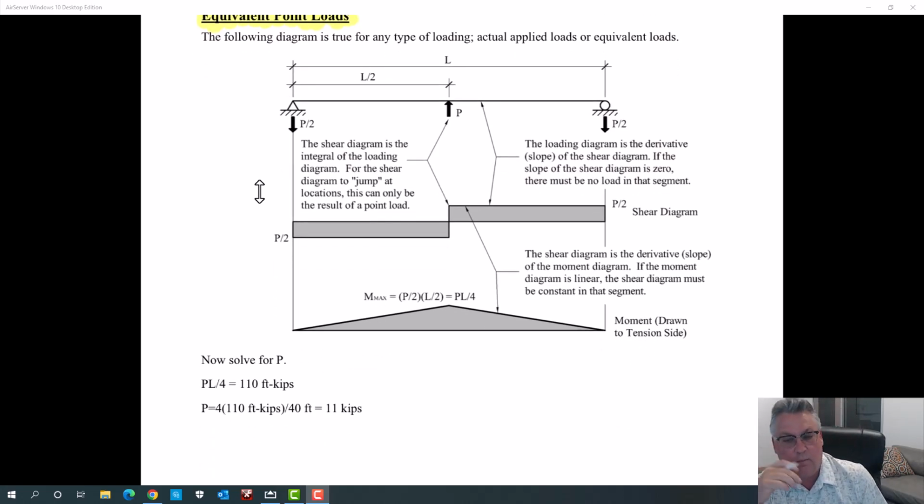Right now you're asking, well, why would you want to do that? It's so easy to just create it, multiplying the force times the eccentricity, but that's what we're here for, and that's what your first couple of homework assignments will show you. But when T.Y. Lin came up with this, it really revolutionized all of pre-stressed concrete. Knowing the force times the eccentricity is the primary pre-stress moment diagram gets confusing as soon as you actually try to apply it to some real type situation. Using another load to create the same effect makes life much easier for us.